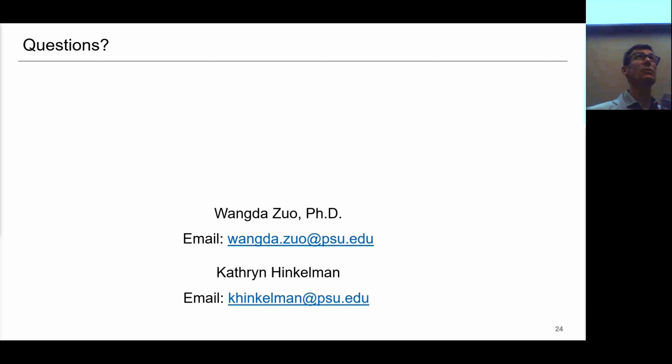This one, I think, uses the electric EIR model or electric EIR reformulated, if I remember right, based on datasheet. But it's always quite a challenge to get those chiller performance data correctly, because usually manufacturers have a very narrow range where performance data is being published.